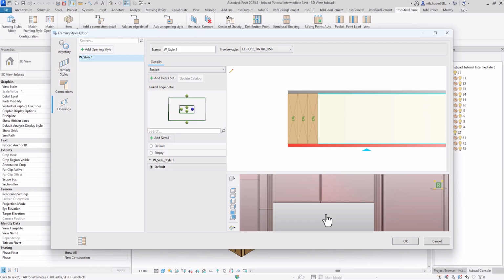And I can quickly explain to you what the goal for this detail is. So, we want to have these two inner beams on both sides going just to the bottom of the header, and we want to have this beam on top of the window. Also, we want to have it stretched to this point and to this point so that it lies on top of the trimmers. Lastly, we want to have another beam vertically to the header detail in here.